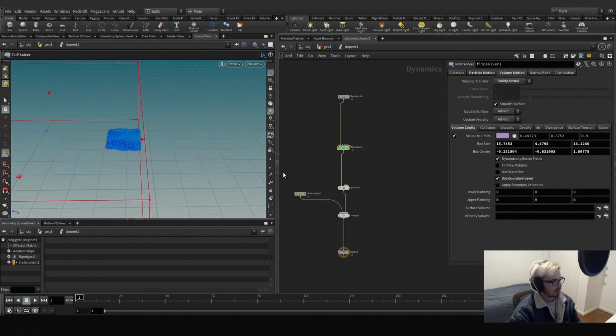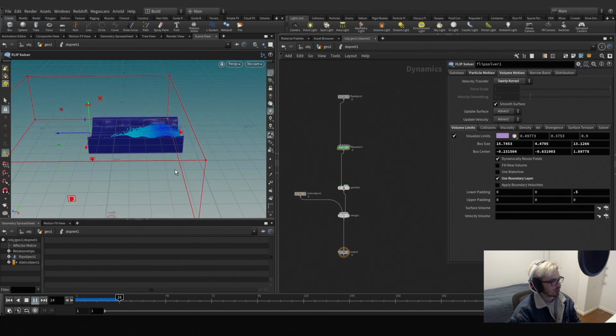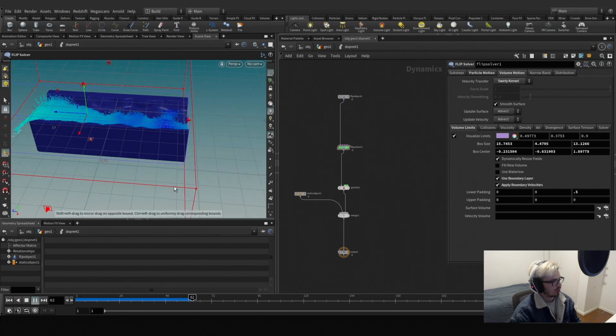And we can have a padding. This will be the lower z-axis, x, y, and z. This should be set to 0.5. So what have I done? Now we should be having on this lower side a place where particles will start advecting over and over and over. See how this is working? And do you see how this is kind of creating new particles?